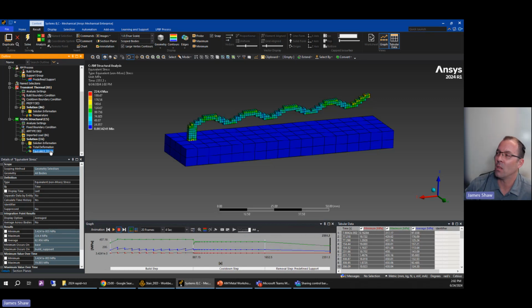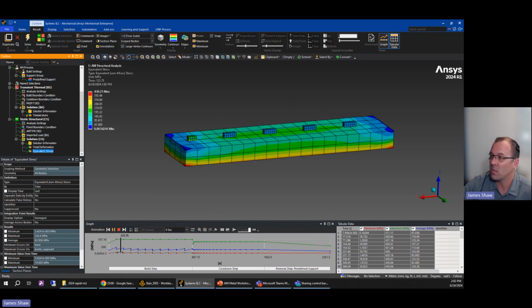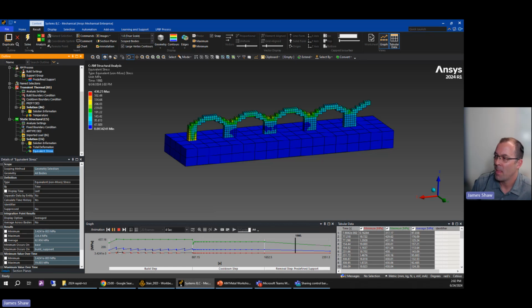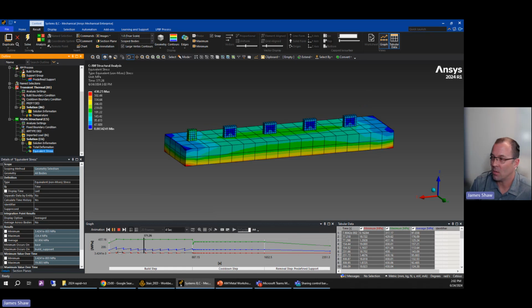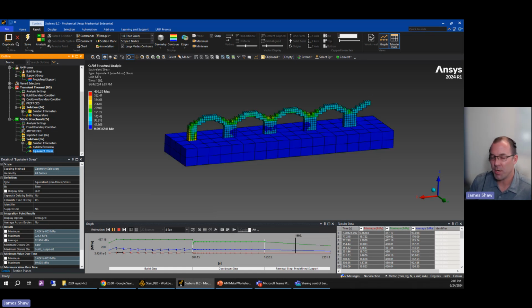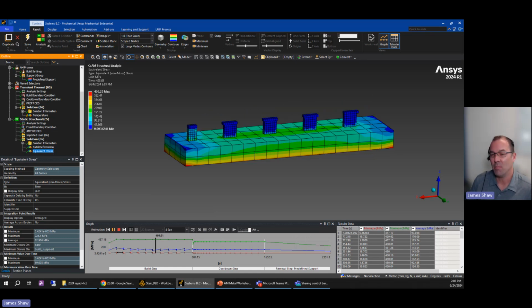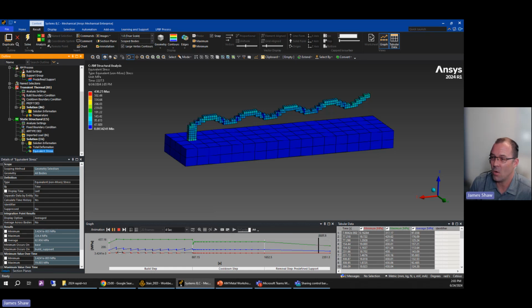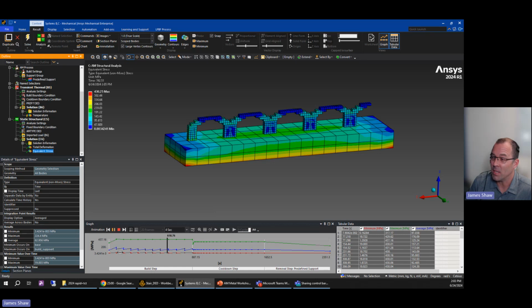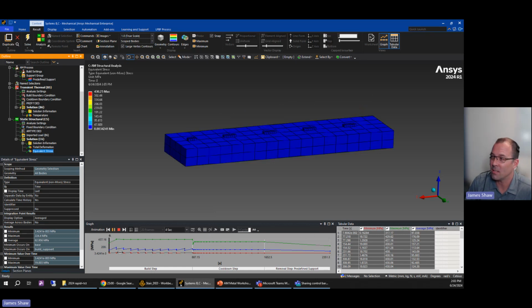And then finally, the last thing we want to look at, of course, is stress, because any structural or mechanical engineer, or your customer, for example, will be very interested to know what the residual stresses are. Let me hit play here. What are the residual stresses inside of this part as we remove it, as we print it, and how can we reduce that? So again, there's this optimization of I want to reduce my residual stresses in the part. I want to avoid a post-process heat treat if I can, but I also want to print it as fast as I can. So anytime, again, we have an optimization opportunity, simulation is a fantastic way to predict that and to make the best parts possible.